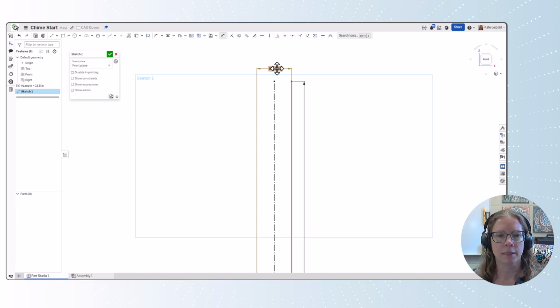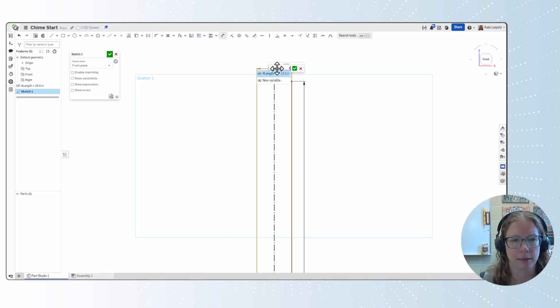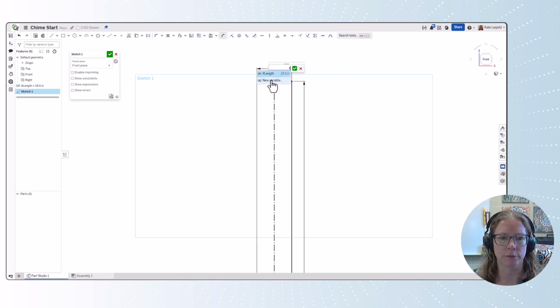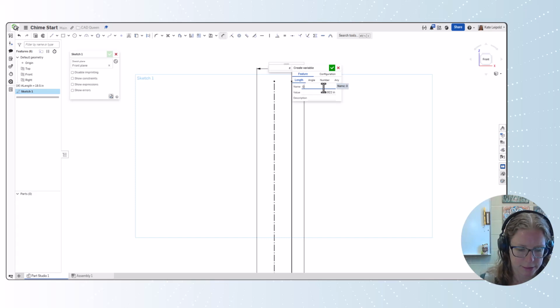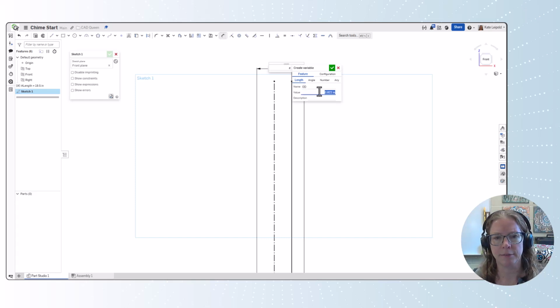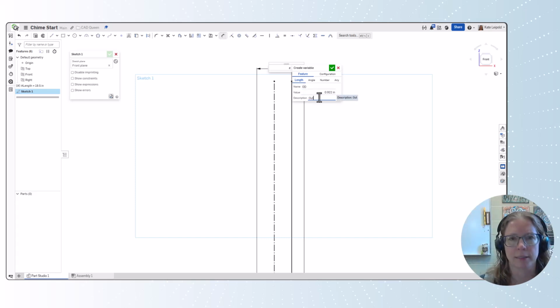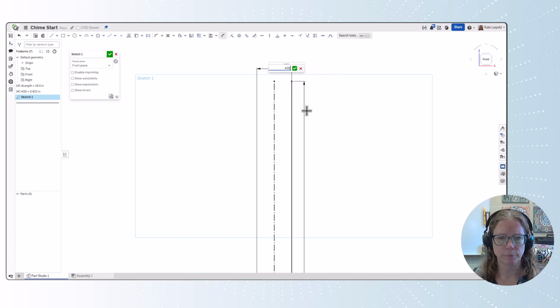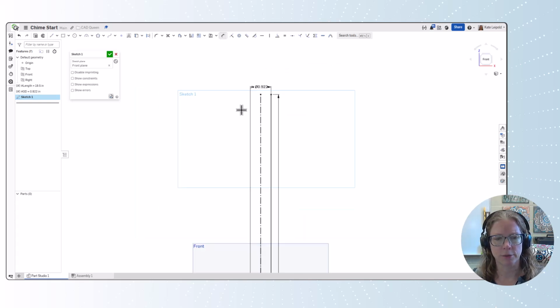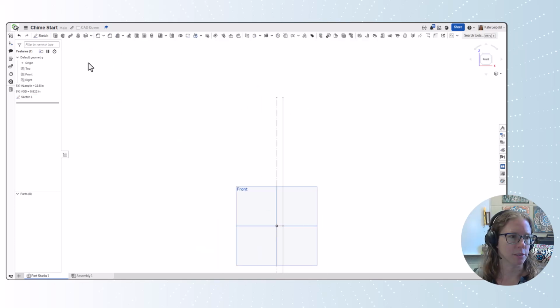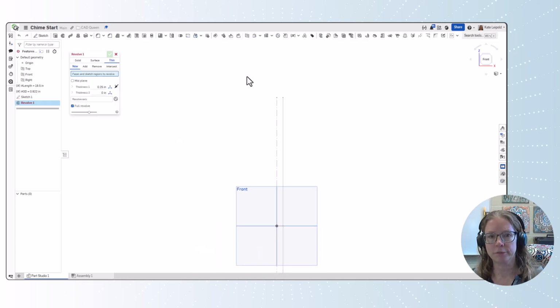And if I really wanted to work with other sizes, I could build that in as a variable. In fact, let's do that. Let's type in the hashtag for a new variable. Let's call this OD. Let's leave the value and give it a description of outer diameter. And actually, I'm going to just write inches, although it says it there under values. Okay. So now we are fully defined in our sketch, and we can use this sketch to create a revolve.